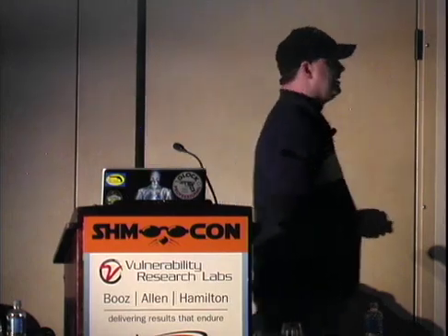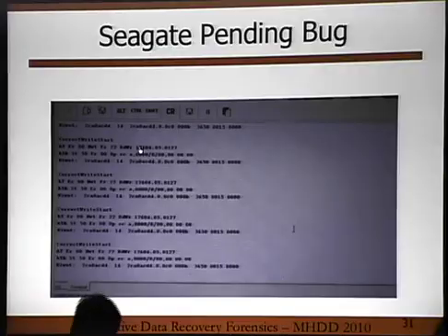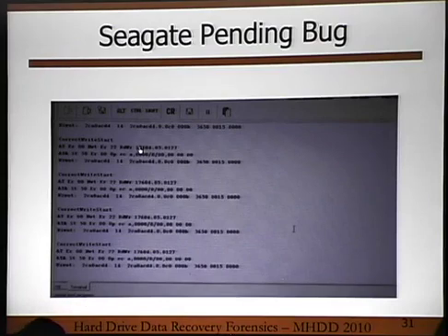If you hit something like a period, it will give you a status line. It will actually talk to the drive, it'll say what is your status, and it'll give you back a health line, and it'll tell you everything it needs to know in one health line. Now you still have to interpret what that means. But all Seagate drives, of all IDE, SATA, 3.5, 2.5, they all have a serial port.